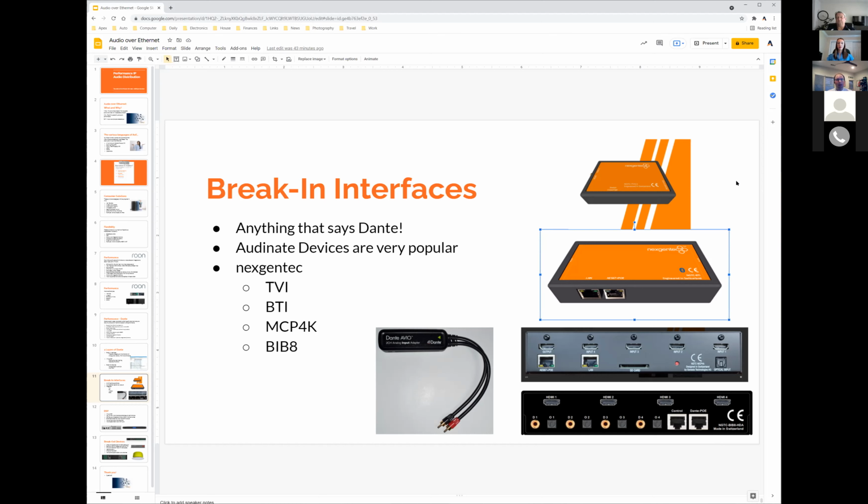So that pairing, that handoff, is done in the virtual DSP. From volume control in the DSP to volume control on your phone, all done on the fly. Transport controls, feedback, everything is available to the automation system as well. So you can have it fully integrated on Crestron. The BTI can also be configured, not to jump ahead, as a breakout device to transmit to wireless headphones. That has been a very, very big problem solver because a lot of times customers have a master bedroom situation where the husband wants to stay up and watch TV, and he wants wireless headphones. This is a perfect solution because you can do all the down mix for surround, everything in virtual DSP.